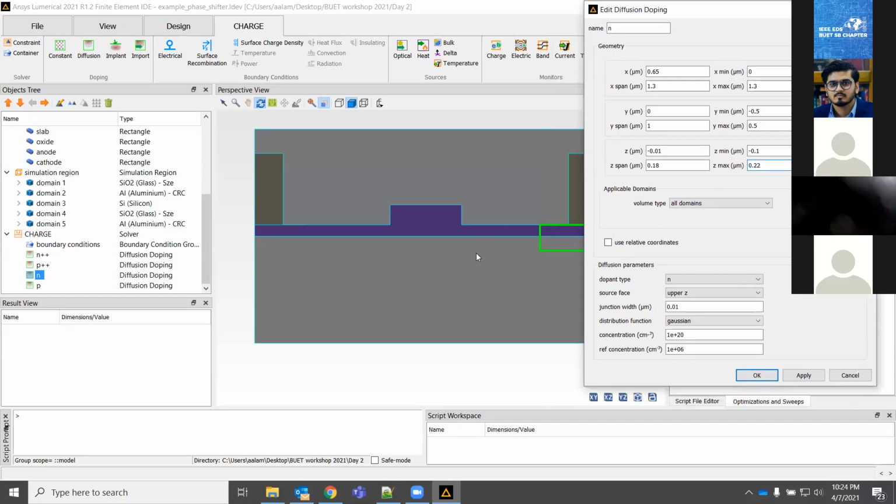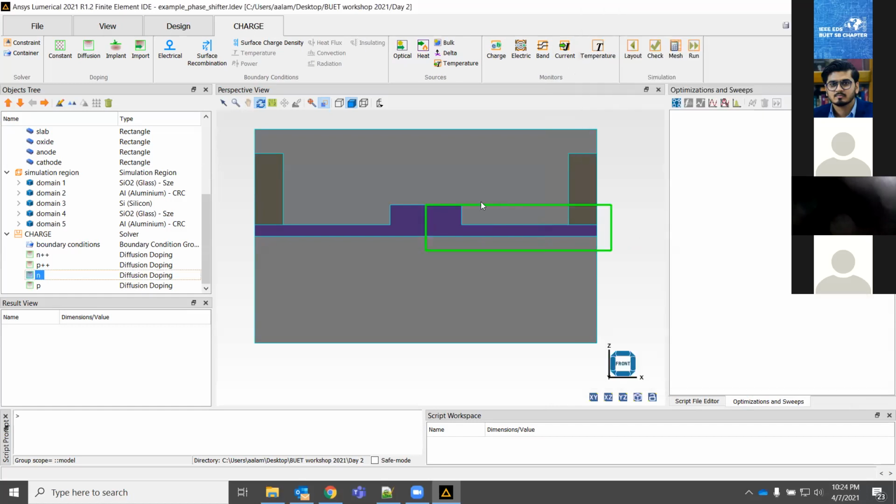And then since in the waveguide I'm going to do a lightly doped compared to the contacts, I can make these 1E17, let's say. So now that's going to be my doping for the rest of the waveguide on the cathode side. Now remember that doping is additive.